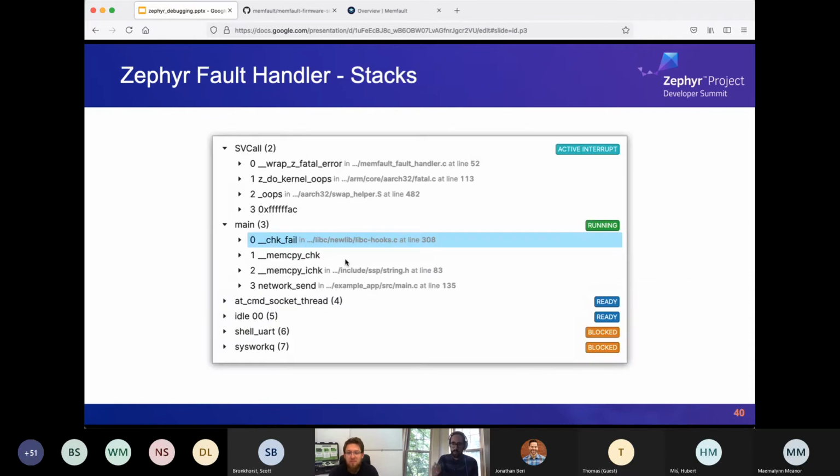The other piece of information that you'll want to have is what was the state of the tasks on the system at the time of the crash. By collecting a portion of the stacks and the registers that were running on the system, we can recover exactly the line of code that the system was running on before the crash and the state of all of the other tasks. Especially in a Watchdog case where you could have a deadlock or some weird blocking between things, you really want the state of all of those tasks to see what was happening.